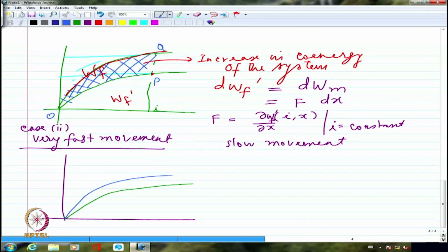Again, let me say maybe one of them is at x1, the other one is at x2. And let us say I am initially at an operating point somewhere here. And I is not a constant. So I am actually going to have rather flux as a constant. Please understand that generally the cause is I and the effect is lambda. Cause is I and the effect is flux.